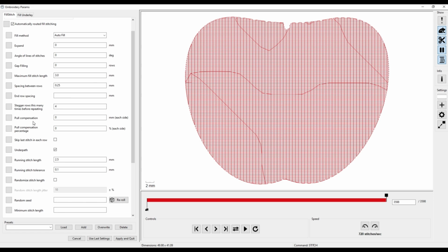However, there are some things we do touch. This is the Pull Compensation line. The name is pretty self-explanatory. When you embroider a design and notice that the fabric gathers or wrinkles, this is called puckering. This can be caused by several things, not by changing the tensioner though, but for example, because the Pull Compensation line is not set. As the embroidery machine sews, it will pull the fabric together. This happens when you embroider something round, which looks perfectly round in the software, but when you stitch it out, you can see it become slightly oval.